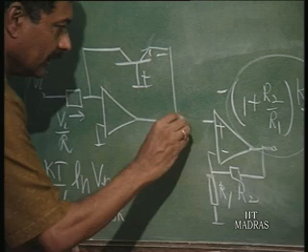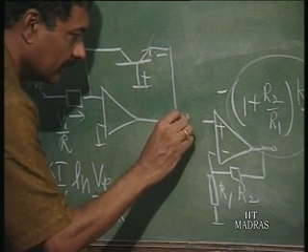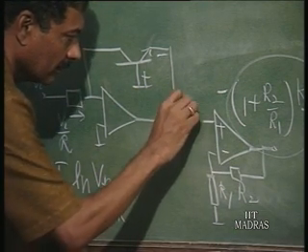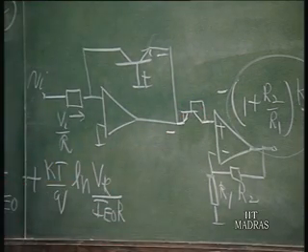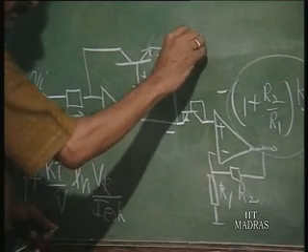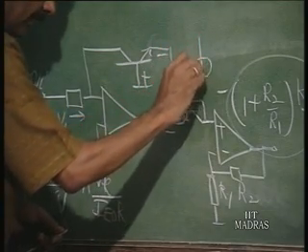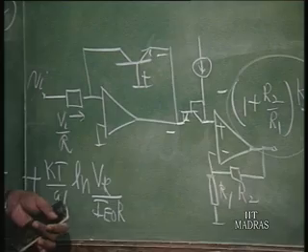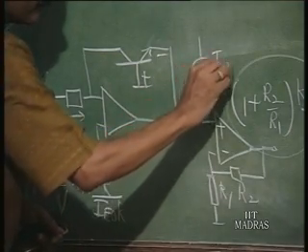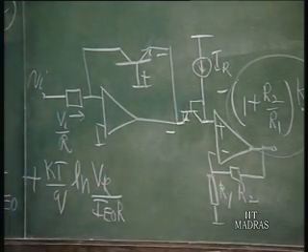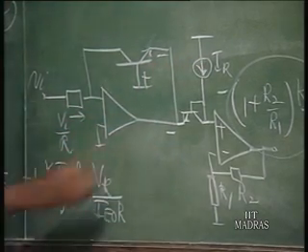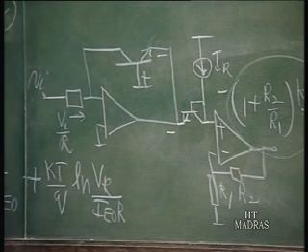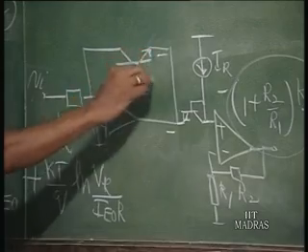So, it will be something like this, let us say, connected as a diode, and I have to pump in current into this, so as to forward bias this by a current source which is going to be carrying a current of I R. So, you can see that this is the way I will compensate for I E naught.